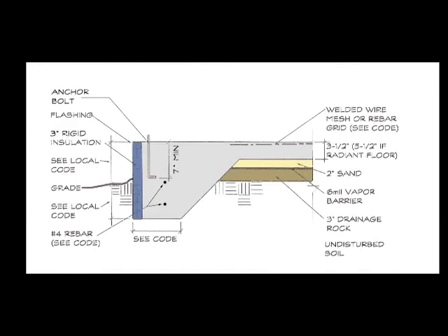On this diagram, you notice that we have the insulation running vertically on the exterior of the concrete. Now the major disadvantage of this is that it creates an area where you cannot inspect between the ground and the mud sill. You've got insulation running clear up from the ground, and termites and other insects have a pathway behind that insulation, potentially into your structure. The advantage of it is that it uses much less material and still creates an insulation value worth noting on the concrete slab itself.